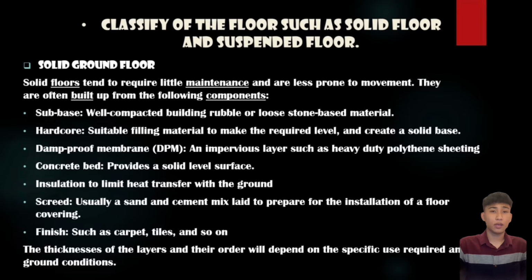Insulation to limit heat transfer with the ground. Screed, usually a sand and cement mix laid to prepare for the installation of a floor covering. Finish such as carpet, tile and so on. The thickness of the layers and their order will depend on the specific use required and the ground condition.